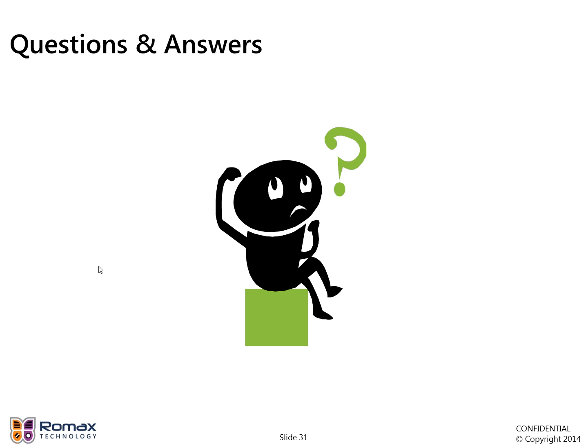Okay, we've got one more question here. How does DynamicFUSION work out what I need in the multi-body model? Okay, that's a very good question. So the level of detail that goes into a multi-body model typically depends on the phenomena that you want to investigate, which in turn usually depends on the maximum frequency of interest. The higher the frequency you need to simulate, the more you need to break the model down into smaller pieces to represent that dynamic behavior. And in that respect, a multi-body model is no different to a finite element model, where of course as you go higher in frequency you need smaller elements.